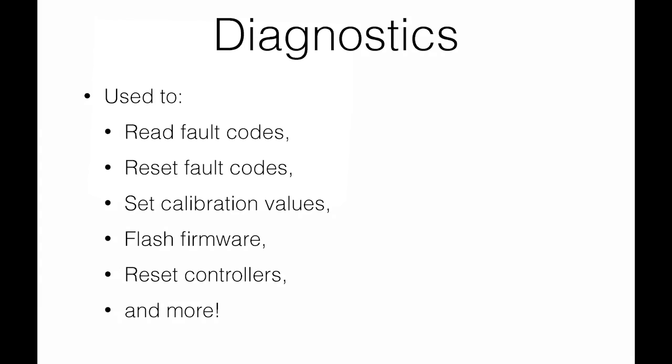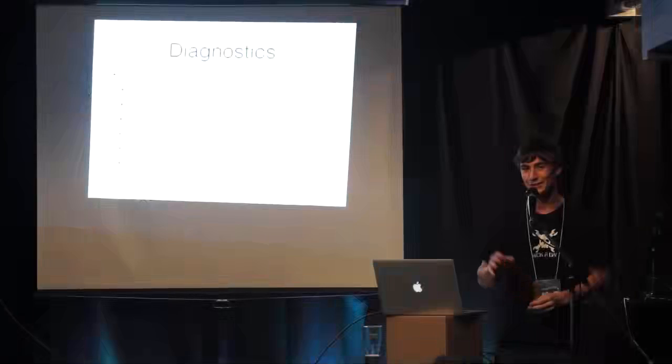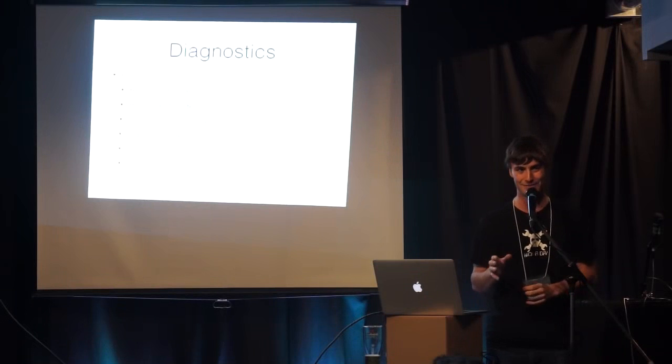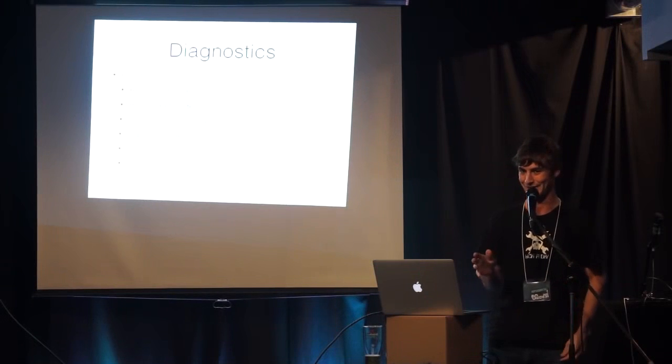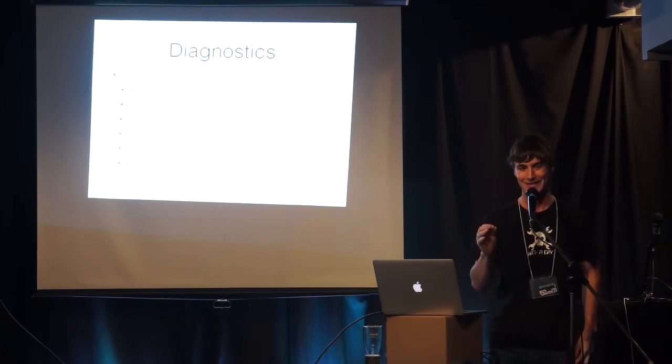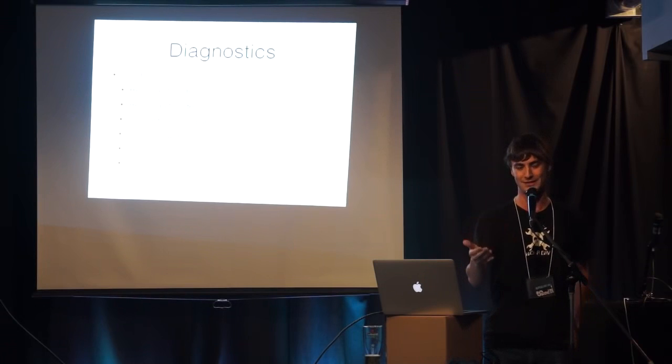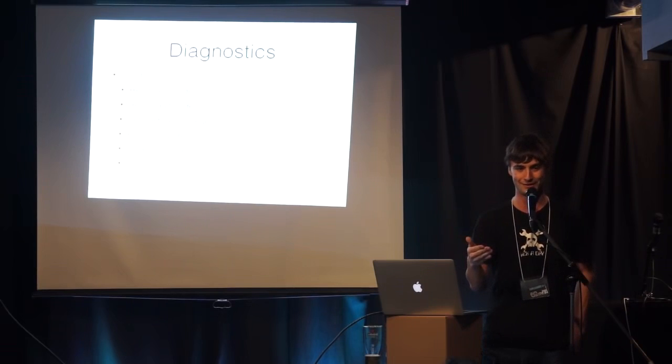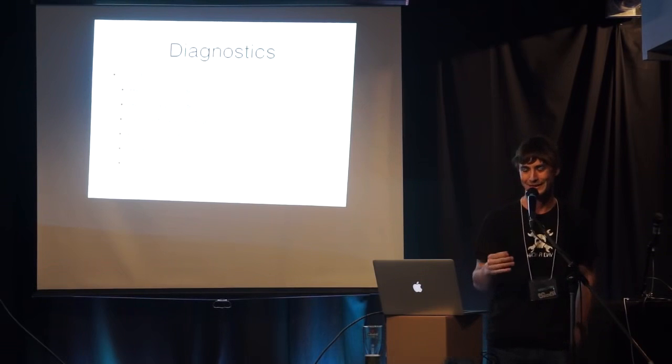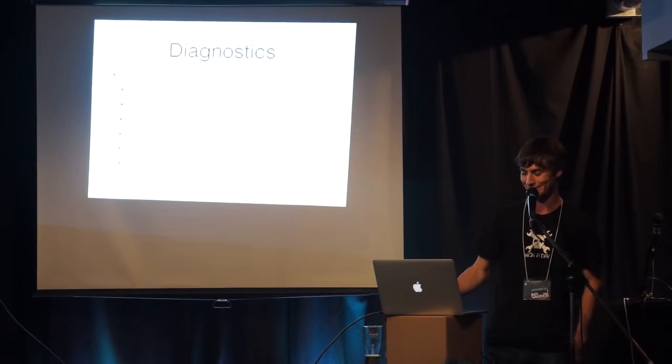But you can also do things like, hey, I'm going to write to where my VIN number is stored on this controller. That sounds scary. I'm going to write to where my odometer value is stored on this controller. Also scary. They do stop you from doing these things with some security, but it's really poorly implemented. It's a challenge response with a fixed seed, so you request the seed, it always sends you back the same value. And both the seed and the key are a whole 2 bytes long. So, not the best security out there.